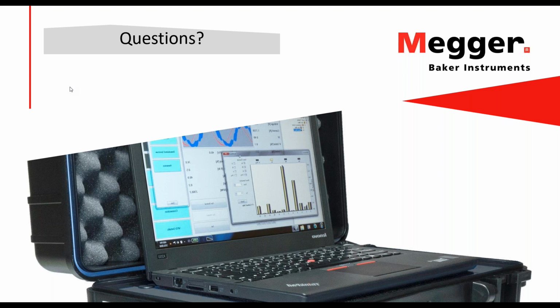However, it is a very bad idea to operate the motor at a voltage higher than nominal regularly, because typically motors are designed to operate with maximum efficiency at voltages similar or very close to the nominal voltage, and also because when you operate a motor at a voltage higher than the nominal, the power factor of the motor will drop, meaning that you will be affecting not only the motor itself, but every element connected to the same mains that you have the motor connected to.